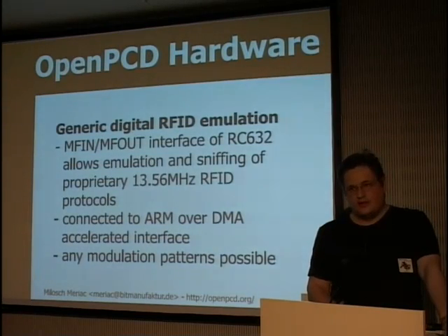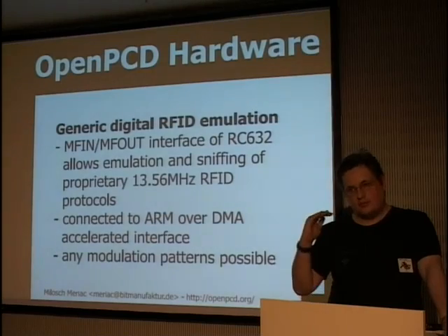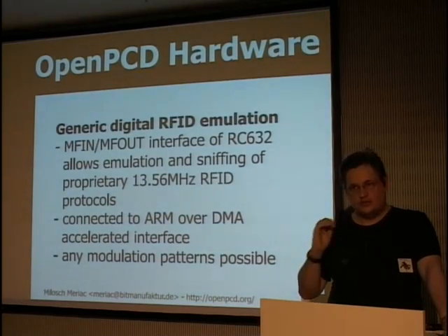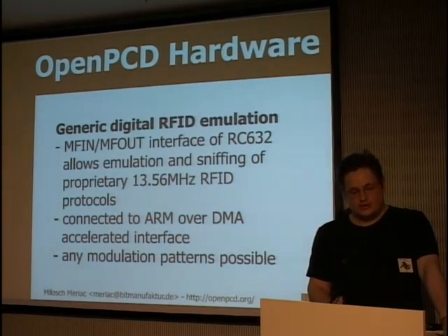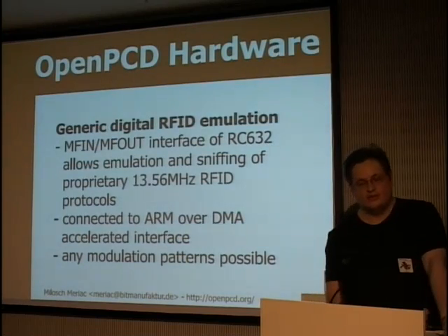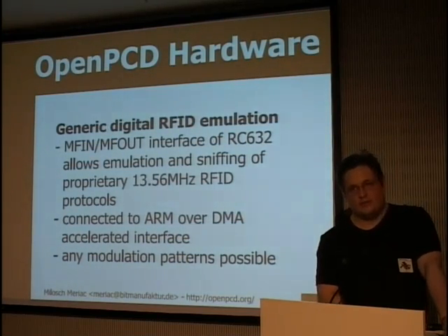The nice thing on this device is if you want to really learn something about protocols in there. For example, you want to see what actually happens on the RF interface when you're issuing commands. You have 2 possibilities. There are 2 interfaces called MF-in and MF-out, and these enable you to see intermediate coding and decoding stages of this RFID front-end chip.